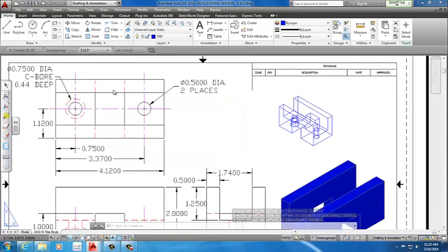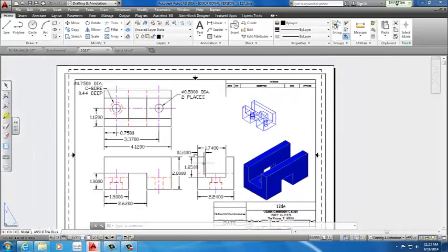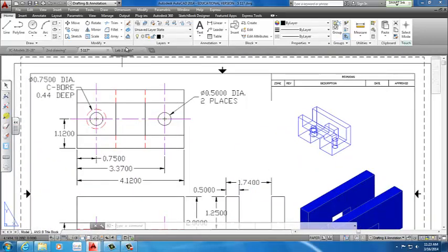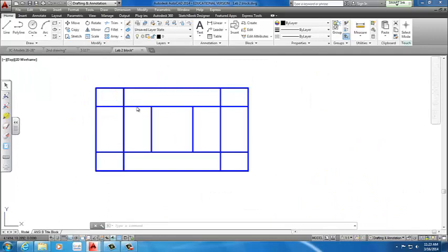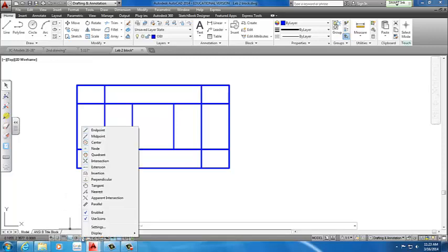But we're gonna create a dimension, which is half of that radius. As you can see, it shows that it's 1.12, which we find out is exactly that, the center. It's actually gonna be 1.62. Kind of obvious, but if you need to check, that's how to check it. So we go back to our drawing. The midpoint of this line is where the circle should be. It's gonna be 1.62. To select that midpoint, I have to make sure my snap midpoint is on. If it's not, make sure it's on right now, and we do the same thing on the other side.